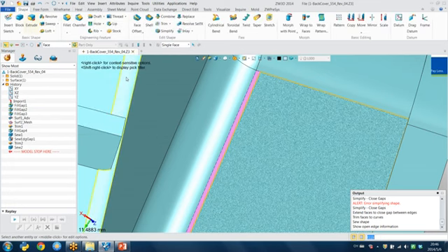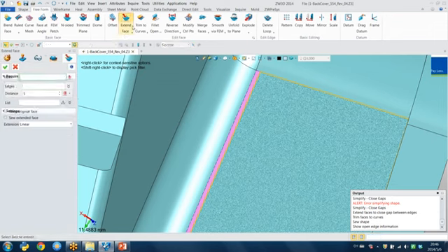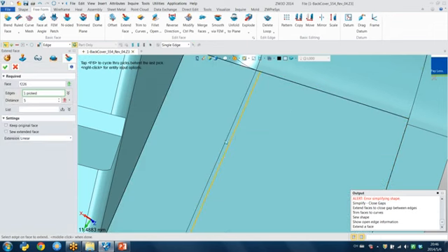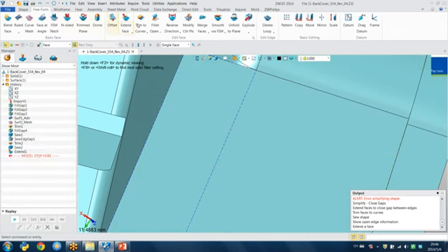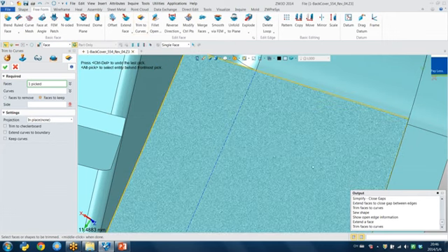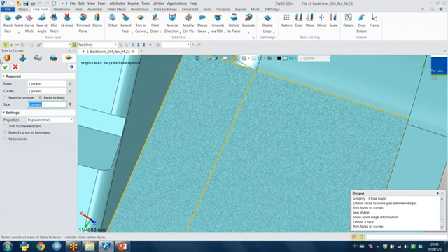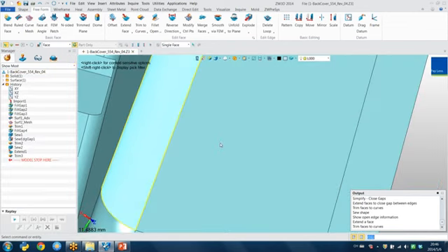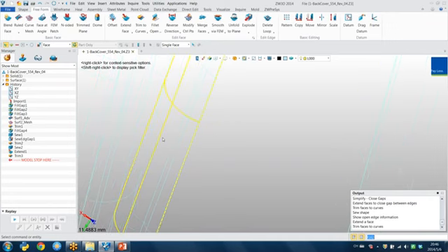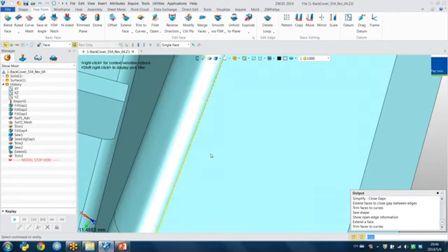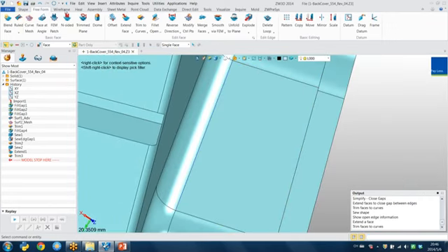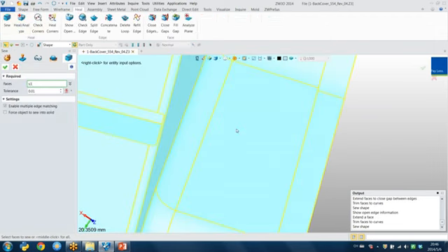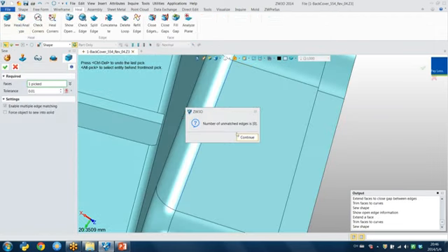Okay, so I can use the extend function. Extend the face, and then trim this face by this curve, and the face to clip, and press OK. This still has one open edge, so I can use sew, shape, press OK.